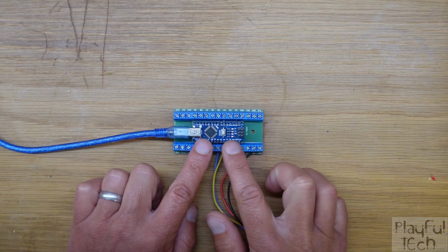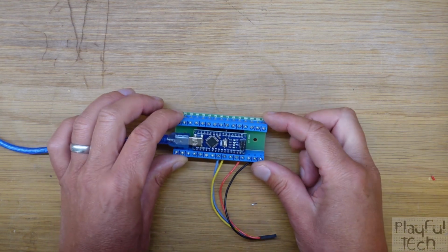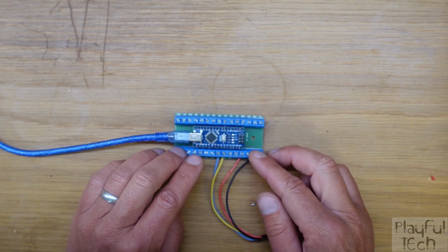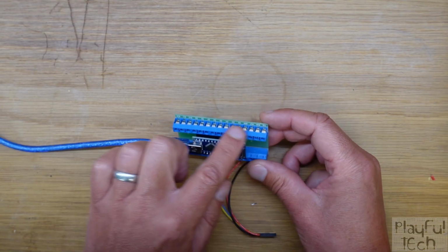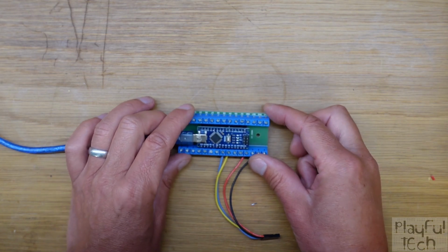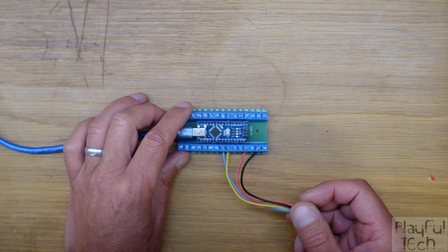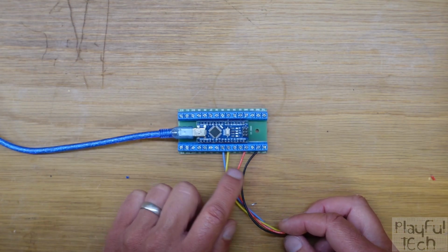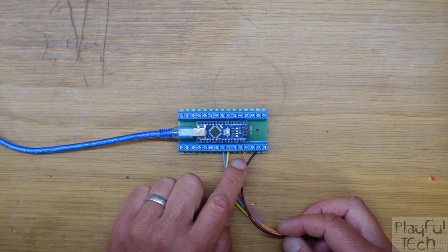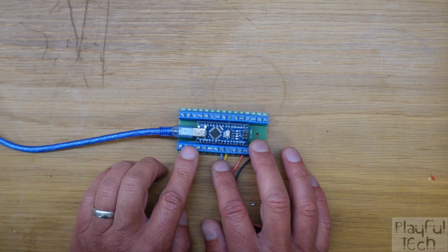Here I've got an Arduino Nano which I've inserted onto a screw shield. This just makes it easier to connect components to any of its GPIO pins through these little screw terminals at the edges. And I've already wired a connector to 4 of those pins, which is using the 2 pins A4 and A5 together with ground and 5 volts. Now, the choice of these particular pins is important.